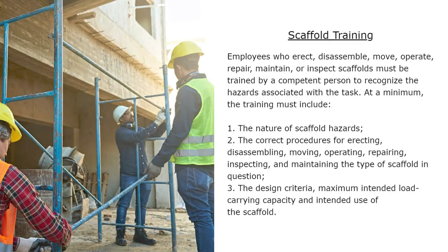Scaffold training. Employees who erect, disassemble, move, operate, repair, maintain, or inspect scaffolds must be trained by a competent person to recognize hazards associated with the task. At a minimum, this training must include: Number 1, the nature of scaffold hazards. Number 2, the correct procedures for erecting, disassembling, moving, operating, repairing, inspecting, and maintaining the type of scaffold in question. Number 3, the design criteria, maximum intended load carrying capacity, and intended use of the scaffold.